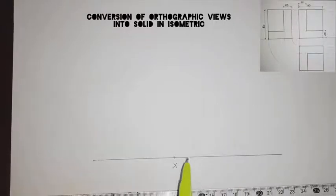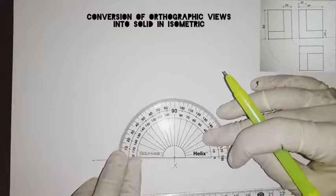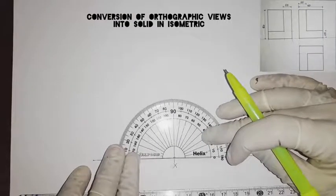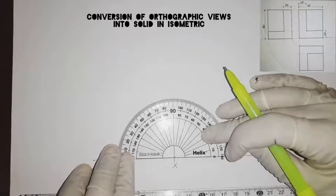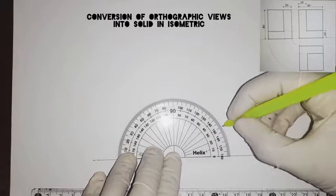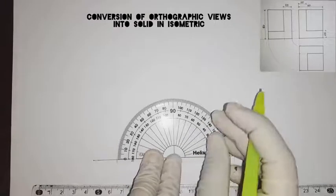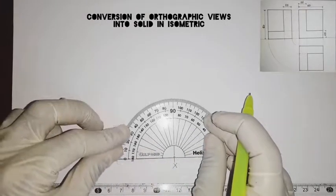Then of course we are going to have that degree line. Let me use the protractor. We may use the 30 degree set square, or we just measure that angle there, 30 degree. But I do recommend the use of the set square because it's already designed to measure the angle. So again, on this other side we need 30 degree.